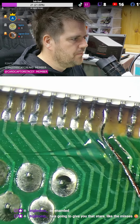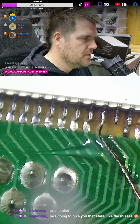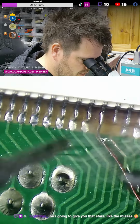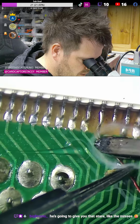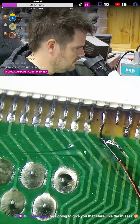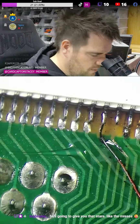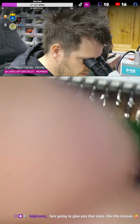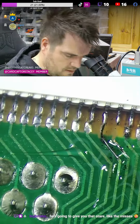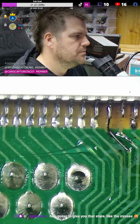And I haven't stripped that wire the best. It's still got a little bit of the red enamel on. But what I'll do is hold it in position and strip it while it's there. So this will try and fly off with all the heat, but there we go, much nicer. So just push down, apply the hot air, and then just leave it for a few seconds and it'll all completely bond and look nice. And then you can nice and easily cut this one. And that's what you end up with. I'd say that's a nice looking one, nice and clean.